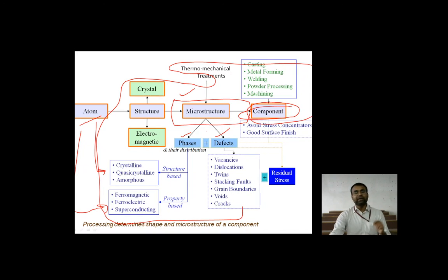When it reached the sea in the cold water at -2 degrees, the phases of the steel's structure started rearranging themselves, and the rearrangement led to a brittle fracture, from ductile to brittle, and that is how it collapsed when it struck the iceberg.